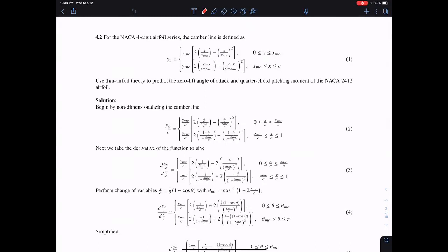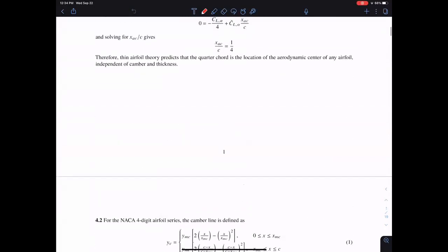One of the challenges, see, it's built on potential flow. One of the drawbacks of the theory is that it doesn't predict any drag, right? Potential flow in general can't tell us drag on an airfoil. And so what we're doing here is we've got some theory that will help us at least predict the lift and the pitching moment that comes from an airfoil. And why would we want to do that?